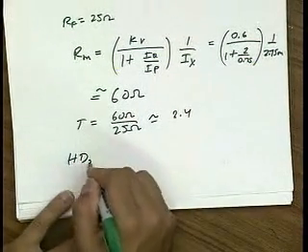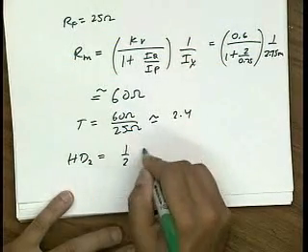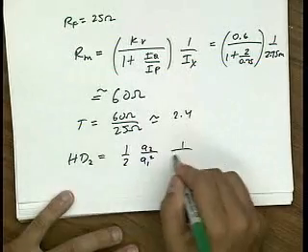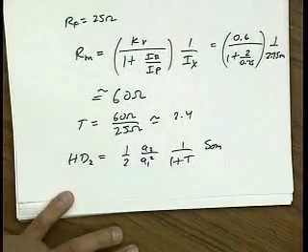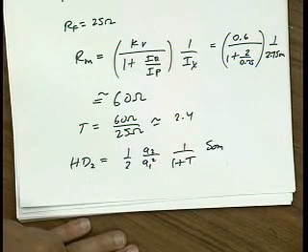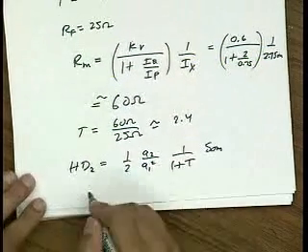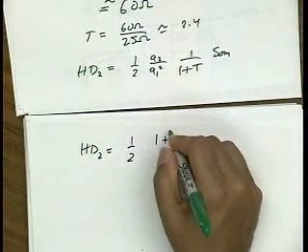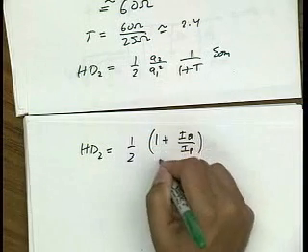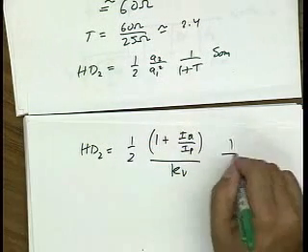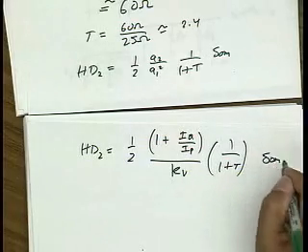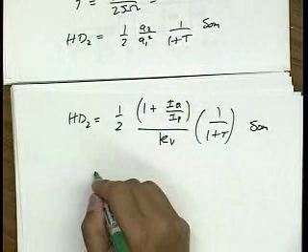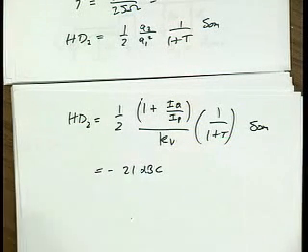And so finally, to calculate HD2, HD2 is nice because it's the HD2 without feedback divided by 1 plus the loop gain. Okay? And we have the loop gain, we have everything. Again, I won't bore you guys with the algebra. We just do a little bit of substitution here. So HD2, which we calculate from the expressions on the previous page. By the way, I'm going to post these solutions online tonight, so you can spend some more time. And if you plug in the numbers, you get an HD2 of minus 21 dBc. Okay? Questions?